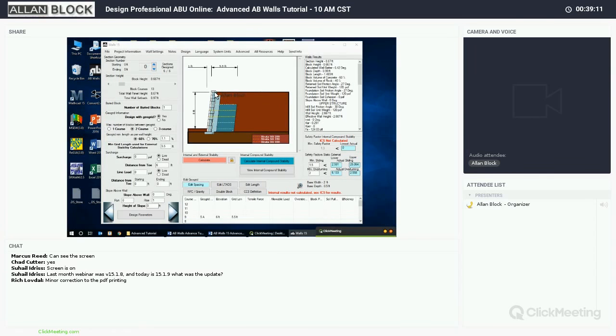Well, if I want to double my wall up, so for example, if I use this double block feature, and here I just start clicking on the courses, notice I'm doubling the thickness. So in this case, I would flip the block end for end, and so it would match the setback, or if you're using the field stone, you could use a longer anchoring unit.